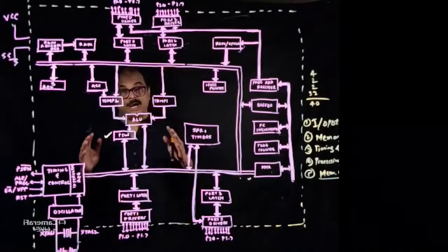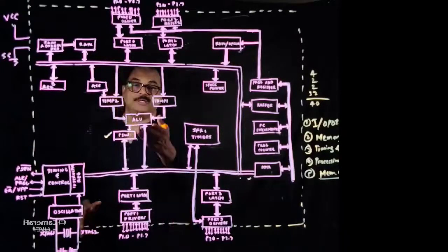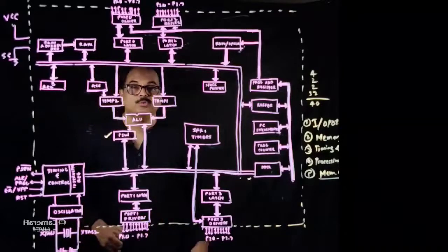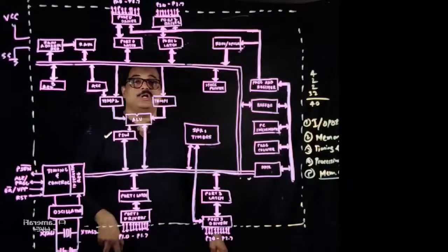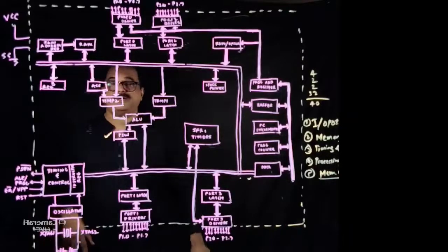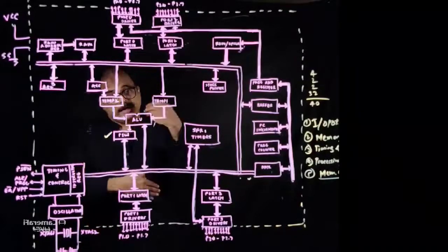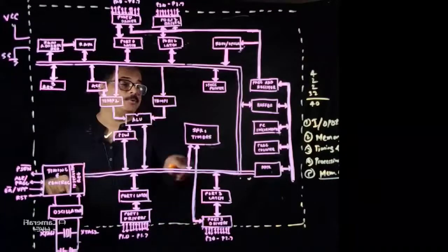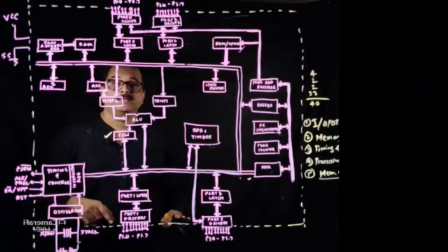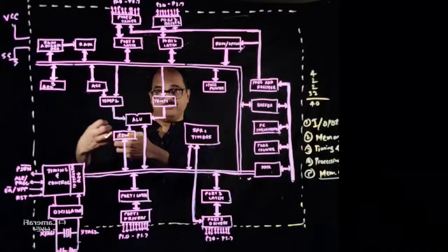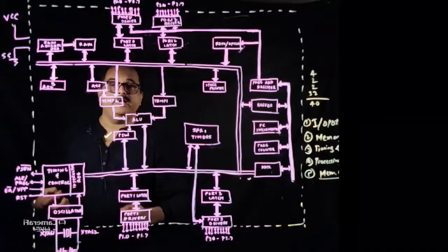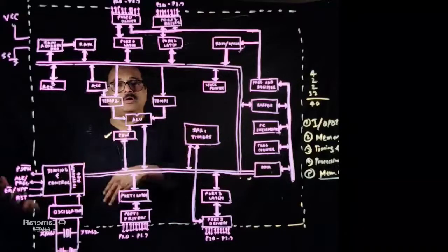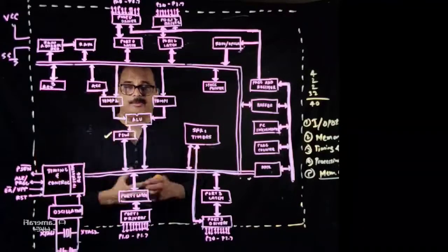processing unit. The heart of the microcontroller is the ALU, obviously the arithmetic and logical unit. The data to the ALU comes from temporary register 1 and temporary register 2, and then that data is processed and the answer goes back to the accumulator, obviously through this internal data bus. So the accumulator gives one of the data to the ALU, and obviously the other data comes from either the memory or any other register and so on, depending upon your program.